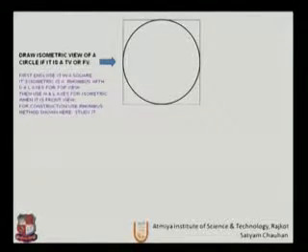So to draw the isometric view of a circle, whether it is a top view or front view, first enclose it in a square. It is isometric, so it will be a rhombus, with the D and L axis for the top view, or the H and L axis for the isometric front view.